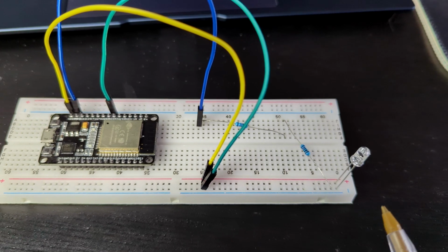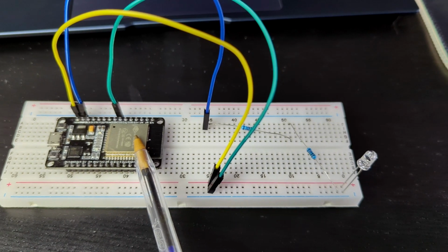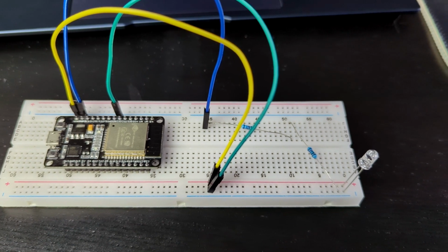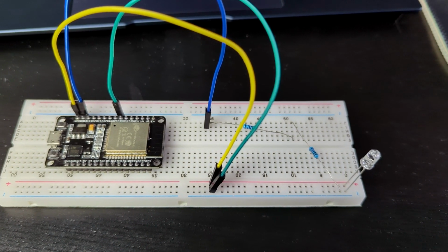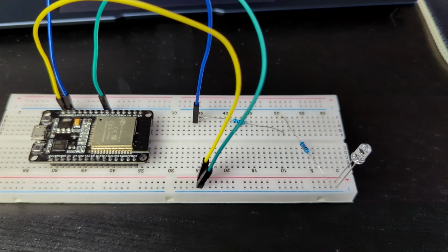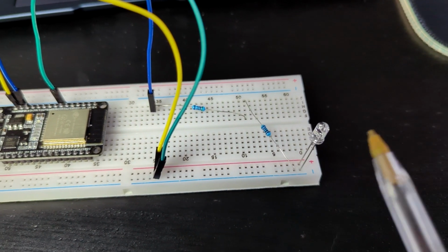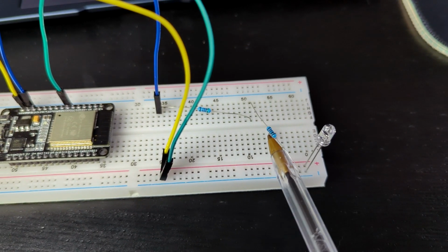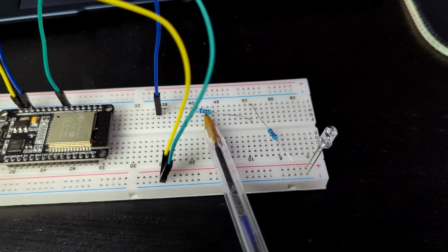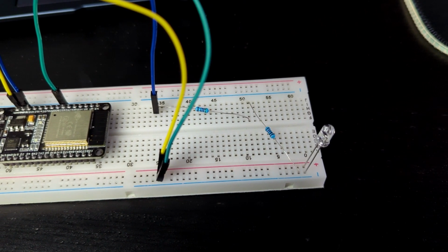And if we're talking about sensitivity and correct work, the possible way is that we always have the signal as zero from this phototransistor, and in this case the ESP32 will always have zero, of course, and it could be the opposite, when we always have the high signal. It means 1 from this phototransistor. To fix this issue, we must set sensitivity for the phototransistor, and for this we're using 2 resistors. In this case, it is a 10 kilo ohm resistor and a 5 kilo ohm resistor. Together we have 15 kilo ohms.